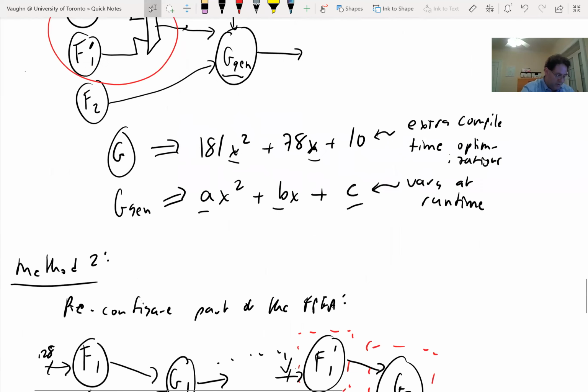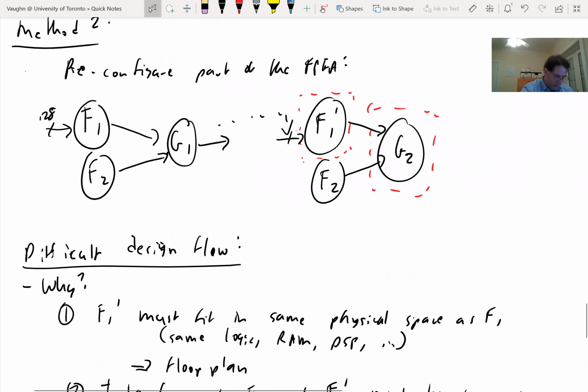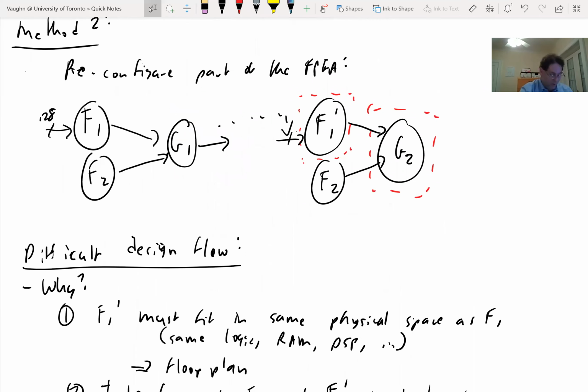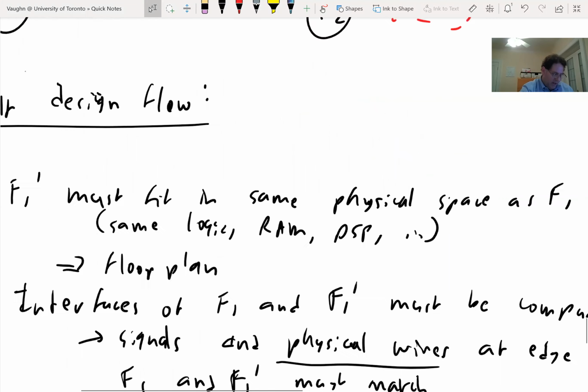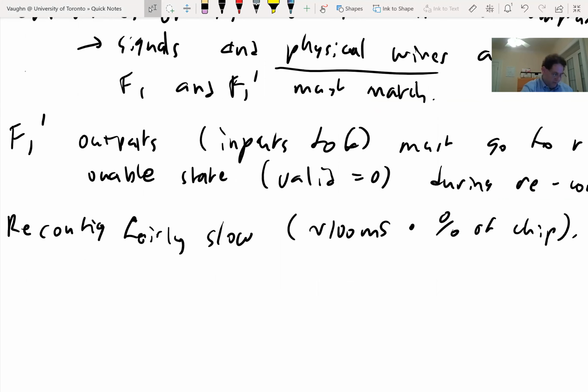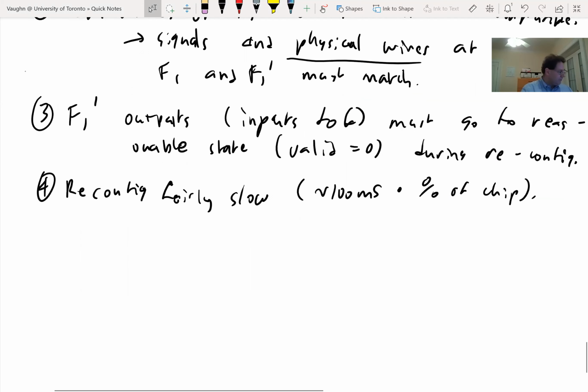If you used a very inflexible compute model where you didn't use valid signals and so on, then you're right, you're probably going to have trouble. As you convert from F1 to F1 prime, the odds of all your latencies perfectly matching what you expected before are lower. But you can, again, deal with that by using a more flexible compute model that uses valid signals, back pressure and FIFOs to deal with the increased ambiguity.